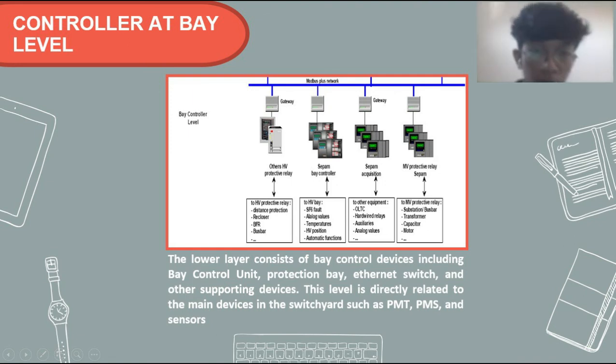Analog output or telecontrol analog or TCA is equipment that functions to produce analog signal output such as voltage level. Next, transducer. Transducer is a device that converts high voltage or high current power from the CT or VT secondary to low voltage or low current output, so that it can be utilized by the analog input circuit on the RTU.